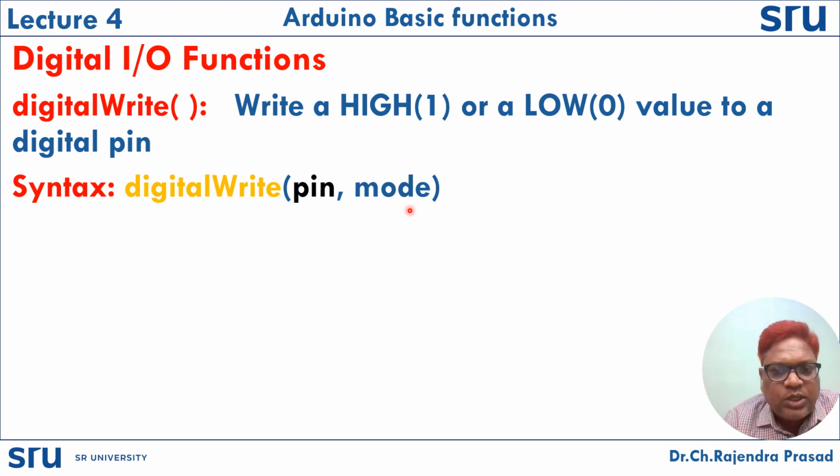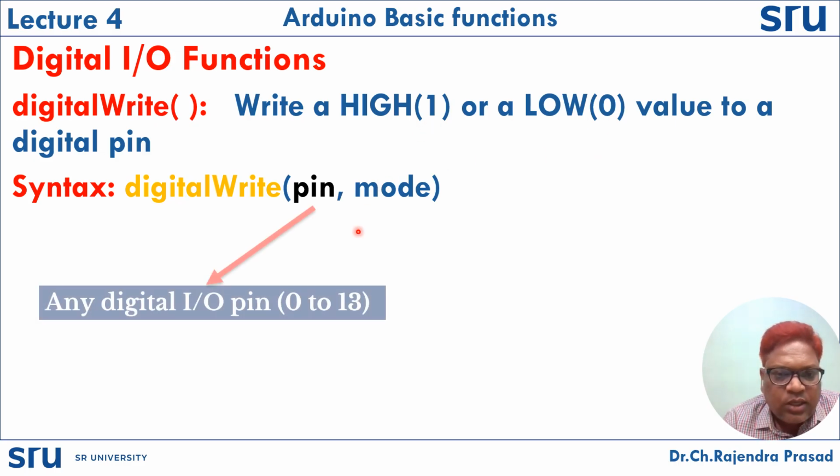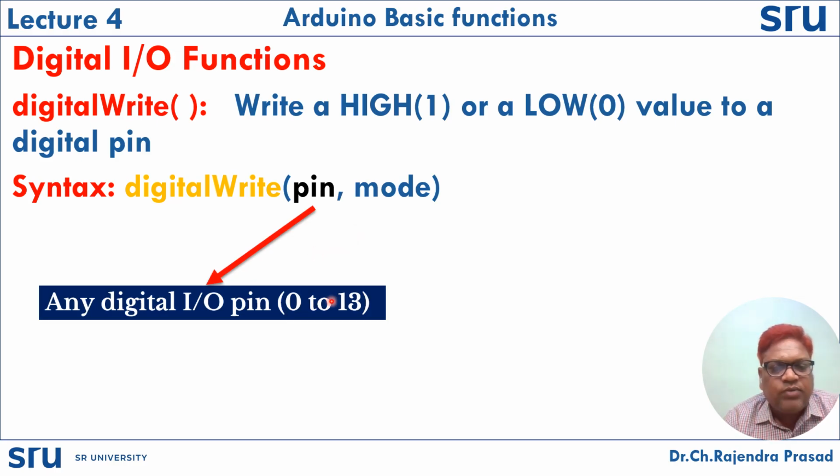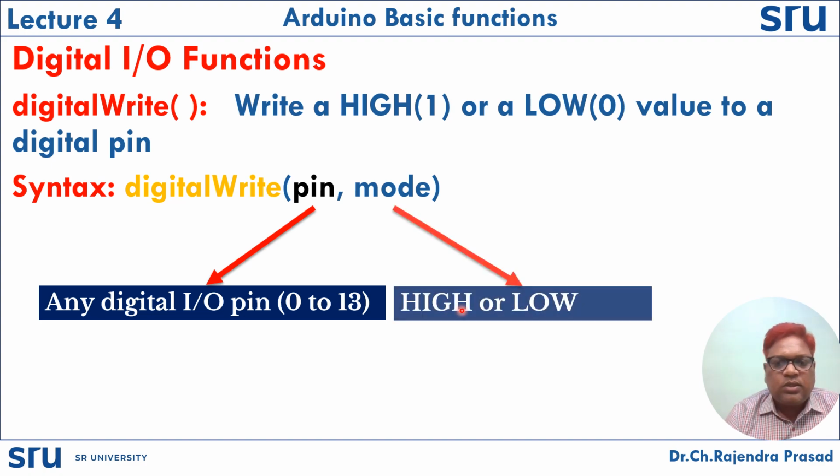One is pin, another one is value, where the pin represents any digital I/O pin ranging from 0 to 13, and the value represents HIGH or LOW. Either you can write HIGH or LOW, or you can also specify logic 1 and logic 0.